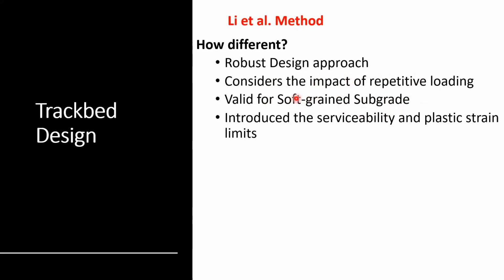At least this is how they developed their approach. But with the right amount of data and the right information, you may be able to extend it, but be a little bit cautious if you extend it to other not soft grained soils like silt clay and intermix, for instance, like glacial till and stuff like that.